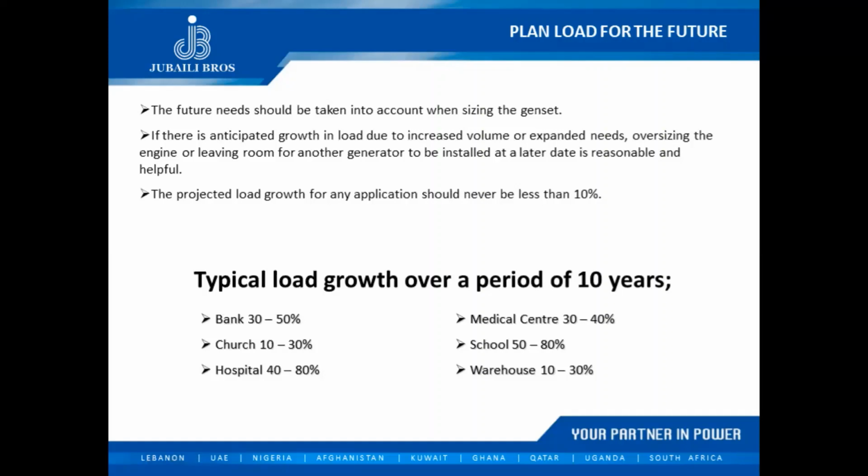So I just added this slide to grab your attention that sometimes we do account for future expansion. What do you mean, leaving room for another genset? No, actually, in some cases you'd oversize the genset to account for future expansion. Just like we sometimes oversize distribution boards and breakers to account for future additions of load, the same applies to gensets.